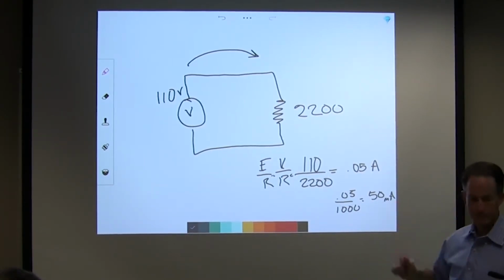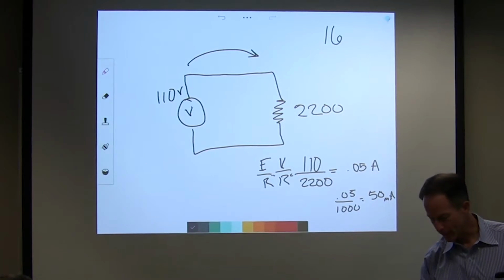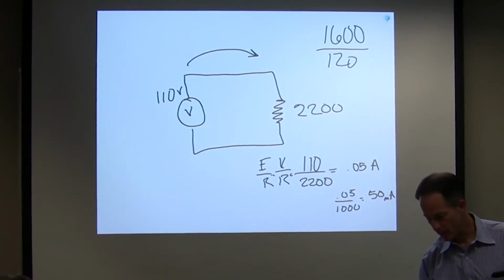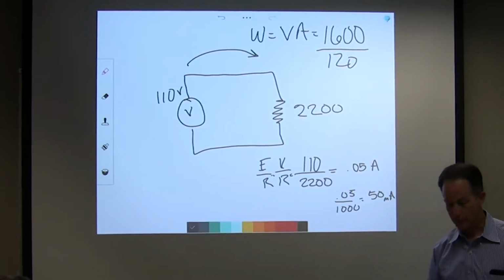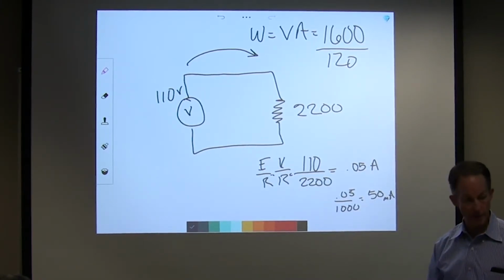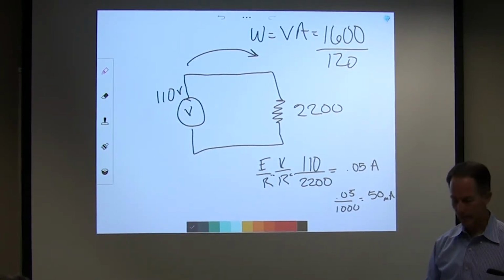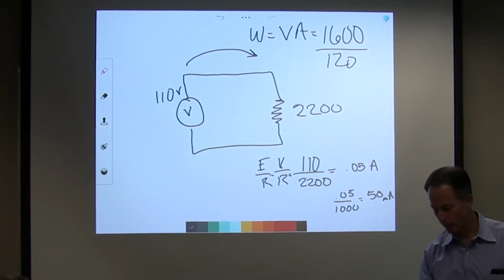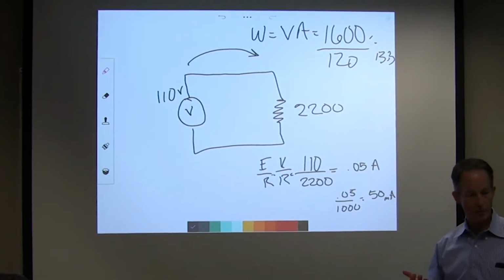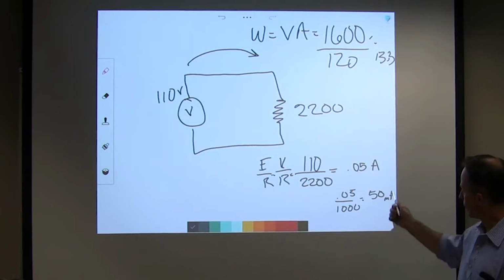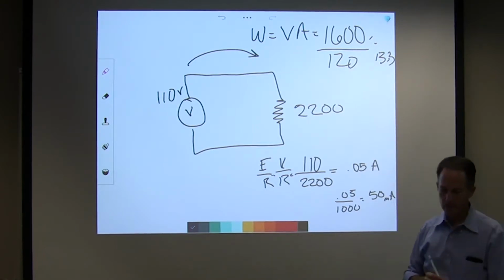All right. So the blow dryer pulls a lot of amps. Yeah. And we would figure that. So say you're 1,600 and you're 120 volts. So watts is equivalent to VA. Your blow dryer 1,600 VA or 1,600 watts. You divide 1,600 by 120, and you're what, 13 something? Yeah. So 13.3. Okay. So that's a lot of amps that it's pulling. All right. So in this case, we're pulling 50 milliamps, so a pretty small load to get this thing to work. Okay.